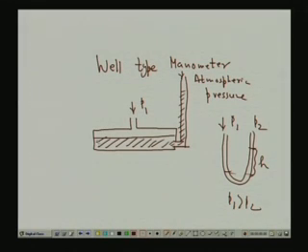Now, here, if the pressure P1 is higher than the atmospheric pressure, this liquid will come down by an infinitesimally small length. So I have to measure only this one h. I should not bother about the difference of height of the liquid in the well, right. Whenever this pressure is relieved, the liquid will come back to our previous position. So this small difference of height we should not bother about. That is the advantage of the well type manometer, or cistern manometer, right.